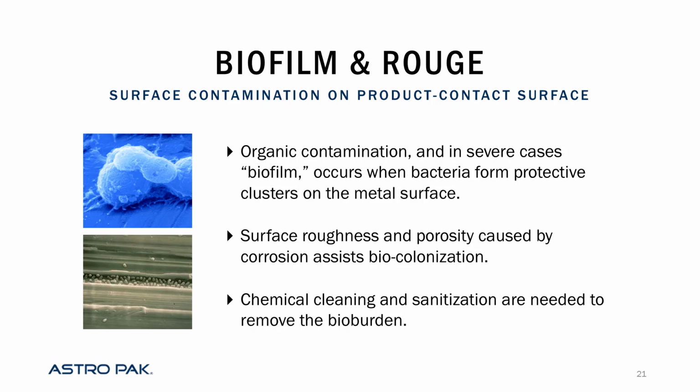A biofilm can occur when bacteria form these protective clusters on the surface, and it's a lot easier to get a protective cluster if they can find microscopic roughness or microscopic pores on the stainless steel surface to live in and eventually grow mature enough to slough off bacteria all throughout the water system or wherever on the process equipment. Oftentimes, a mature biofilm may be too strong for normal sanitization practices, and stronger chemical cleaning beforehand may need to be used to fully remediate a mature biofilm.